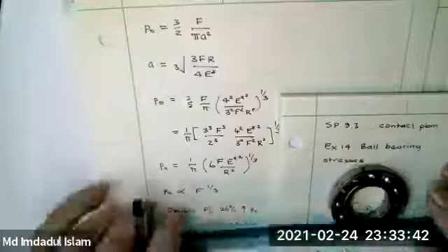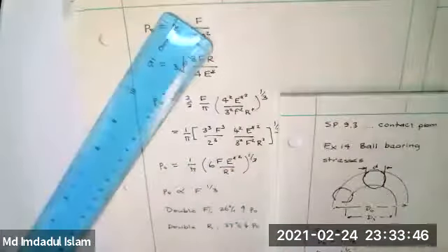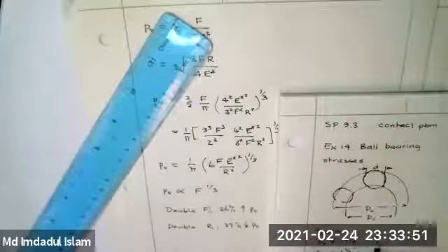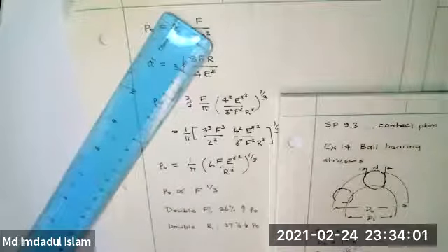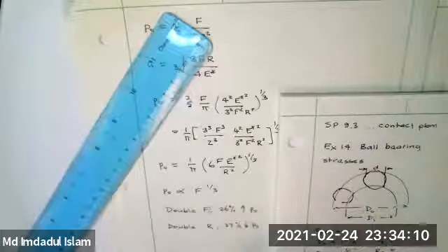Again, they're not completely trivial to measure because there's a casing around them. I estimate them to be about 3/16. So this means, let's call this R1, be 3/32. And R2 here will be half of 1 7/8, be 15/16.